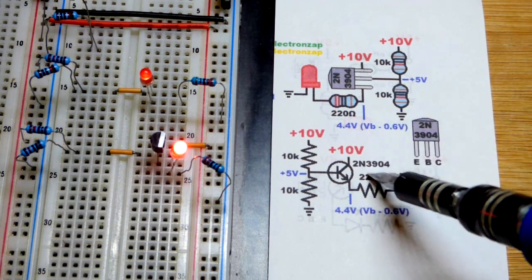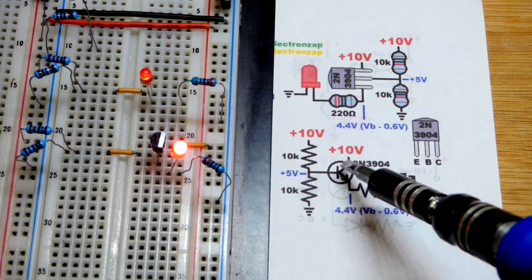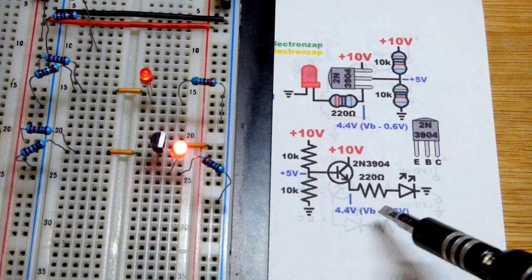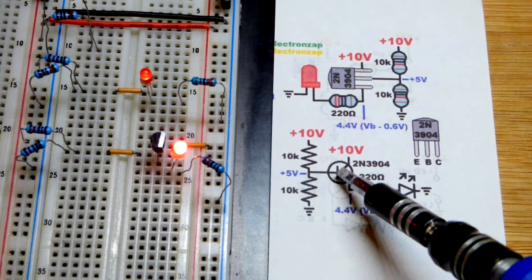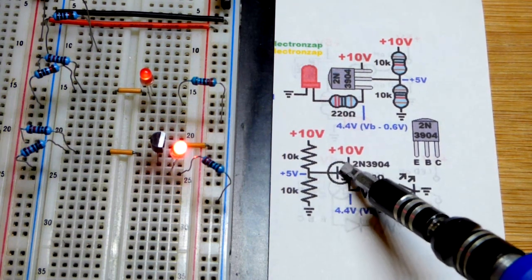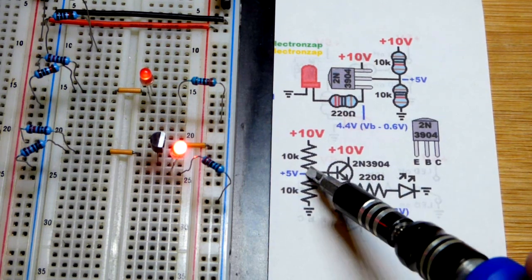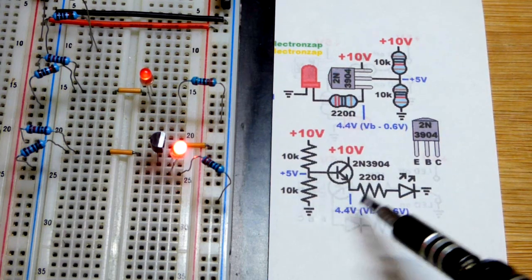So this is an NPN bipolar junction transistor. The arrow is pointing out. Some people say NPN, not pointing in, when it comes to the arrow. So in any case, we got 5 volts set at the base. So now really no current, I mean a little trickle, but very little current is flowing from base to emitter. So the voltage is going to hold really well at our voltage divider.